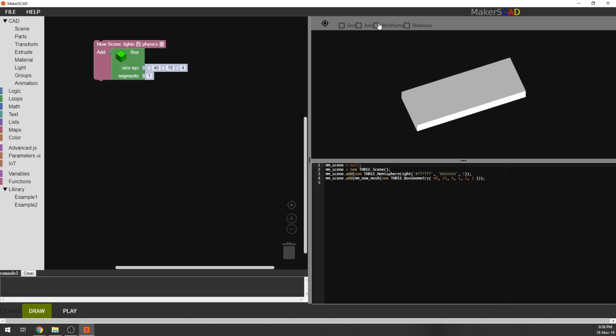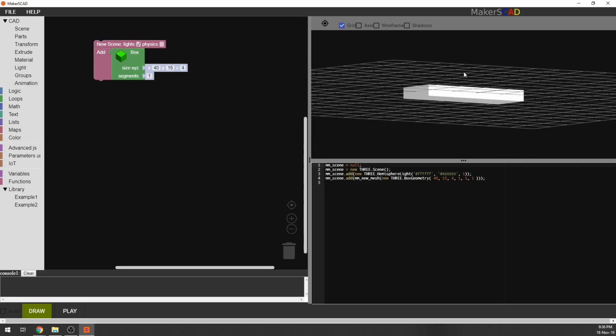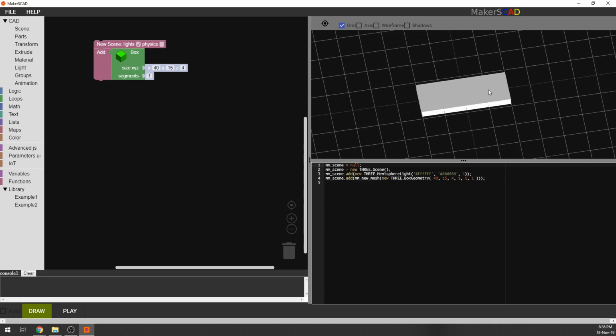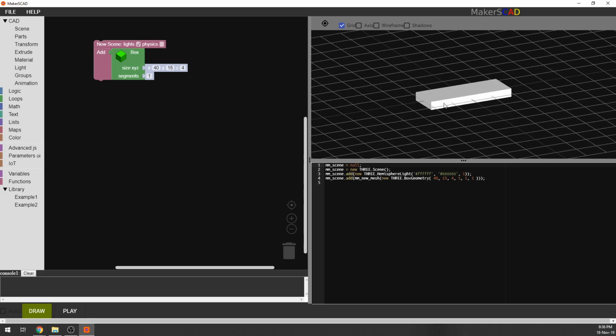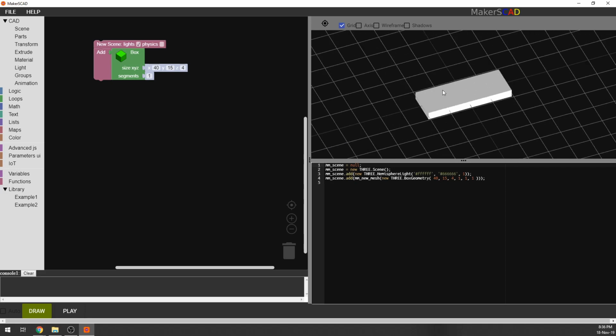So now that I have it here, I'm going to turn on the grid so I can see all the size. So the first thing, I want to add my name here. We can cut it out or we can add it to it. And second of all, I want to put a hole here to put the keys, the keychain over there. So first I'm going to add multiple parts, and at the end I'm going to mix them with this boolean part we just saw.